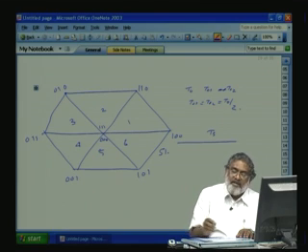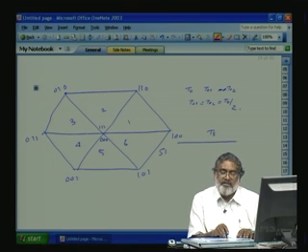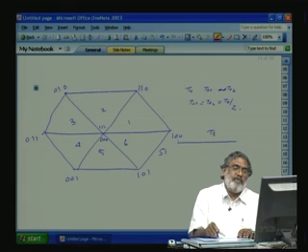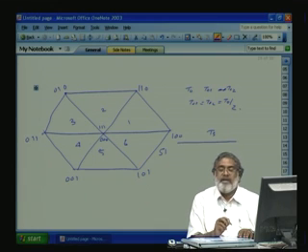The sequence starts from 0 0 0. First is T01, which is 0 0 0, then it will go to 1 0 0. Here only the A phase is switching. Then 1 0 0 to 1 1 0, so here the B phase is switching. Now, for the last zero period, 1 1 0 will go to 1 1 1. So during a sampling period, with minimum inverter switching, only one inverter transition takes place at a time.